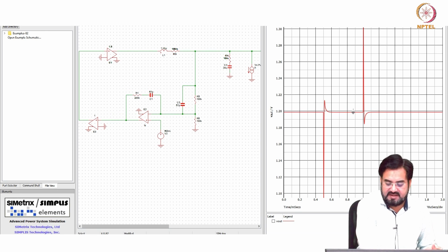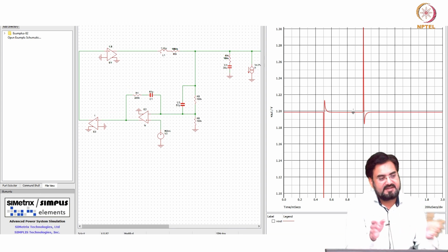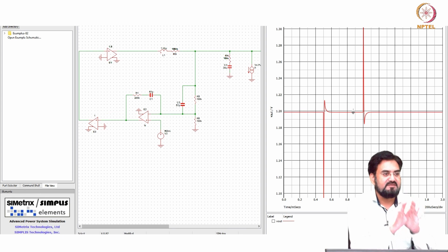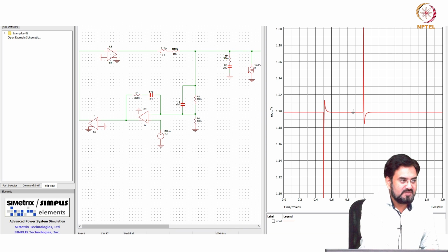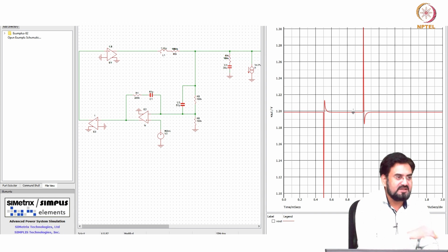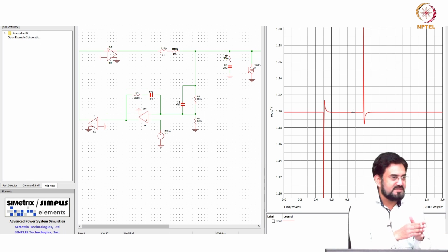No, phase margin is fine, you will get phase margin because Q is reduced. But let us say then you adjust everything, your zero, and you get the same phase margin. What about transient response? You do not remember? Transient response should improve, because your slew rate will be higher for that current. So when you change the duty cycle, your current in the inductor can change faster.